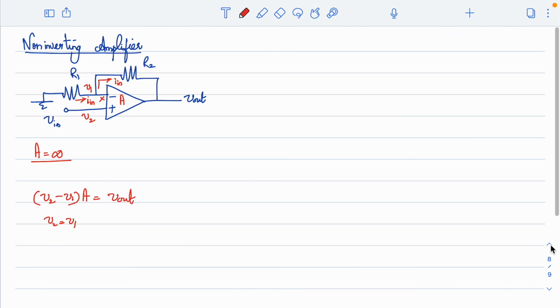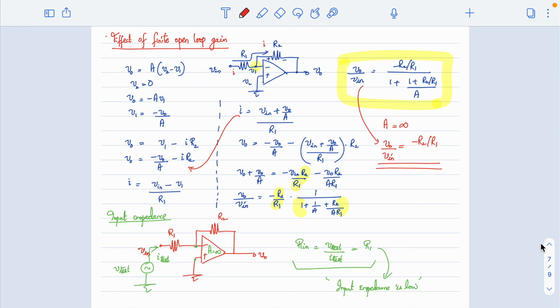Sanket, you have a question for the previous thing? Alright, so here, when I look at the output impedance of this, how will you find this? We will short the input, then we connect a test voltage here, and then we will find the impedance, right? Yeah, we can say that, because when we short this to ground, it is exactly R2, but with feedback it will be still smaller than that, because it will be reduced by that factor. Already by looking at the output side you can say that. Yeah, that is true.